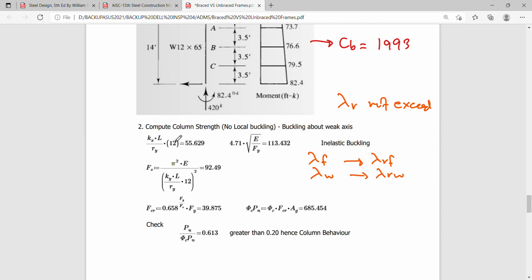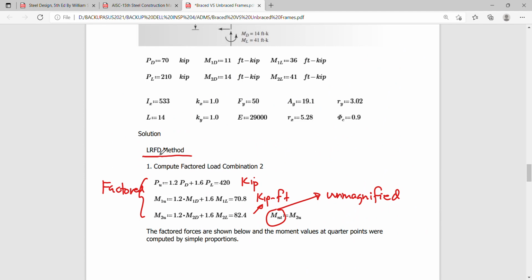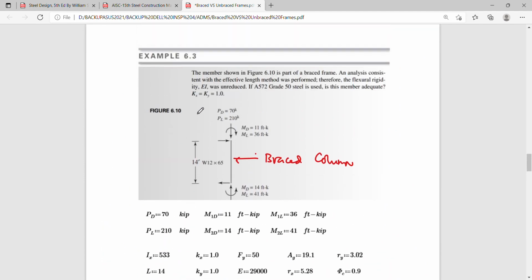So this is now your weak axis slenderness ratio. So this is slenderness, a ratio of the weak axis ry. So this is actually Ky L over ry. Fortunately, your Ky and Kx are just, I think, the same. I think they are just the same as 1.